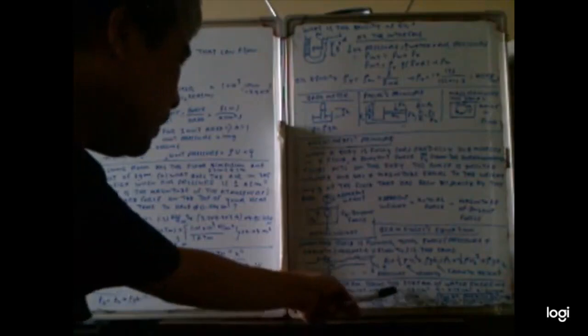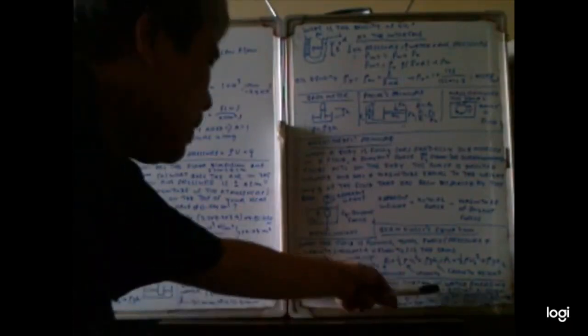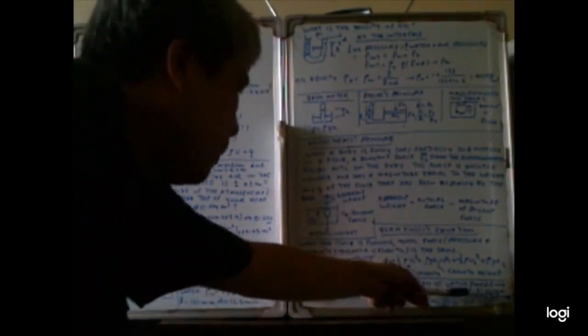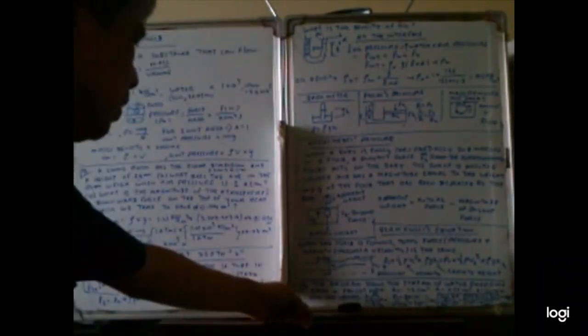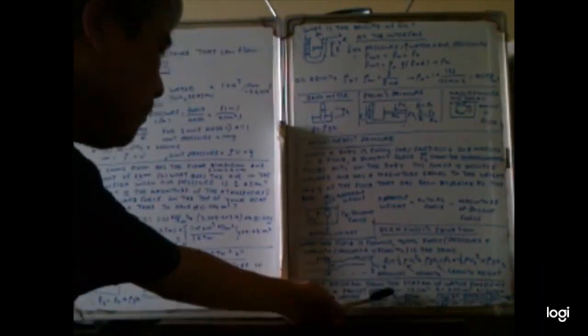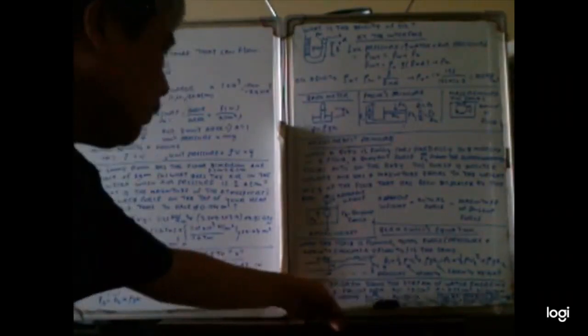In this problem, the diagram shows a stream of water flowing from a faucet. A0 is 1.2 centimeter squared, and A is 0.35 centimeter squared, at a distance of 45 millimeter. You have to find the volume flow rate. So this is the quantity you have to calculate. V0 is the square root of... so A0 V0 equals A v.